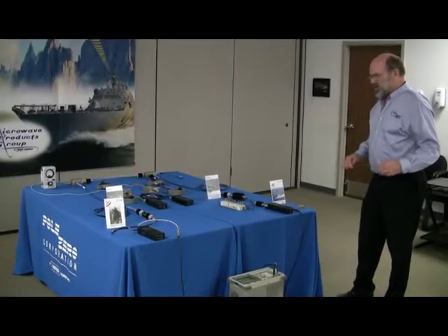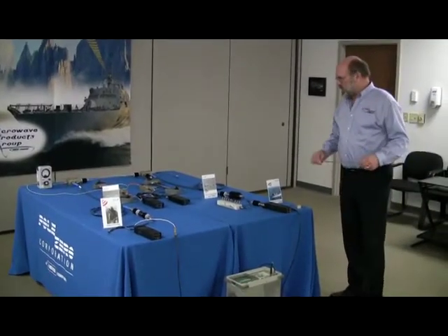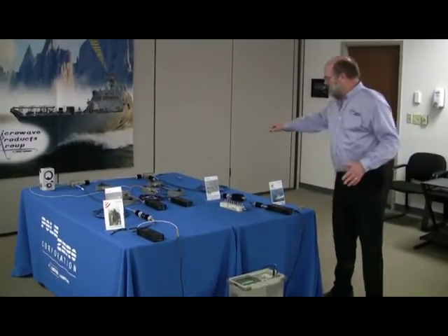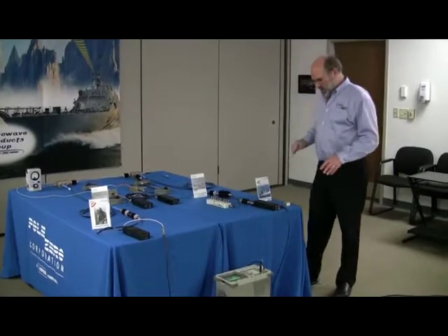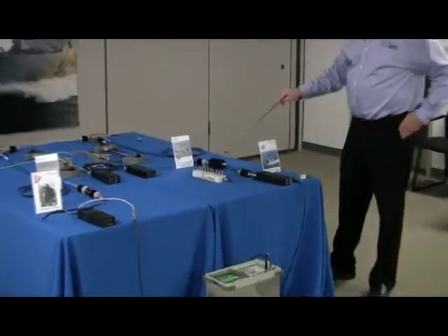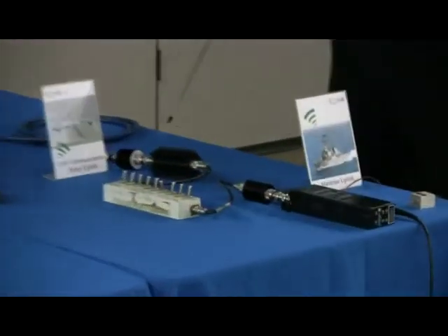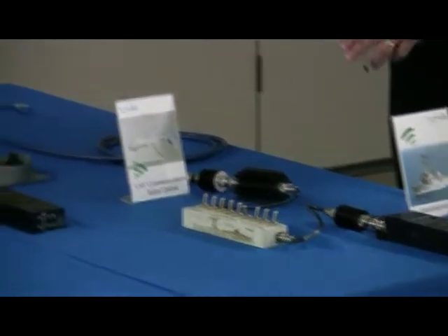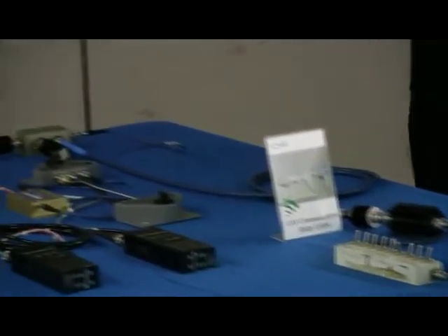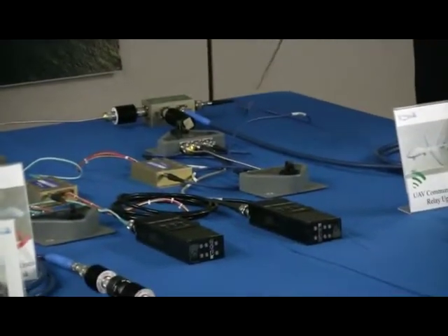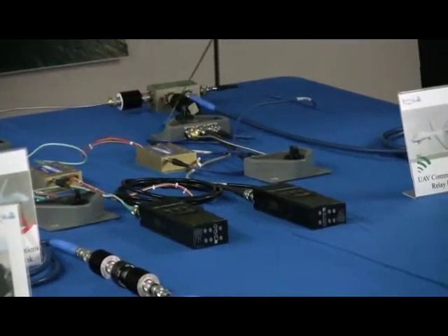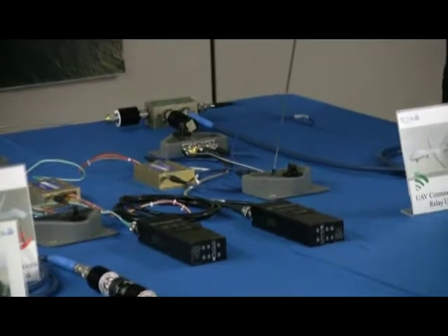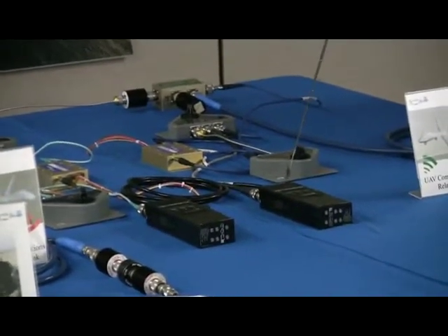All right, let's begin to do our demonstration here. Recall that the uplink is basically on this half of the table and the downlink is on the other half of the table. This is the uplink transmitter. Its output goes through a network of fixed and variable attenuators, couples into this switching matrix here, which either can bypass or apply the Cosite mitigation unit, but ultimately the signal goes to the uplink receiver.